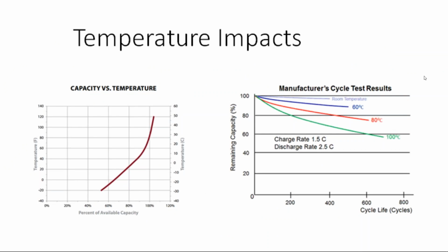And so what we see in battery spec sheets is, here's the freezing point right here. What we're seeing is your flooded lead acid can actually get below freezing, below 32. Can even get much below 32. So here's the battery being rated down to negative 20 before it starts freezing, with the caveat that when you get into those negative temperatures, talking Fahrenheit here, you have to keep the battery at least 50% charged.